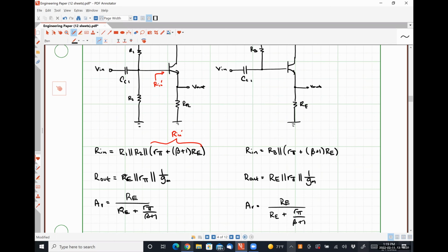But once we get to our actual amplifier analysis, it's literally this exact same stuff, except that we're going to have a different subscript on our resistors, okay? The only appreciable change in our small signal analysis is the fact that for a MOSFET, the thing between the source and the gate, much like the thing between the base and the emitter, is a capacitor instead of a resistance.